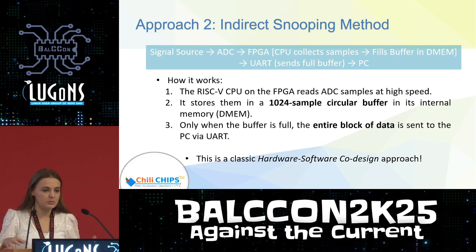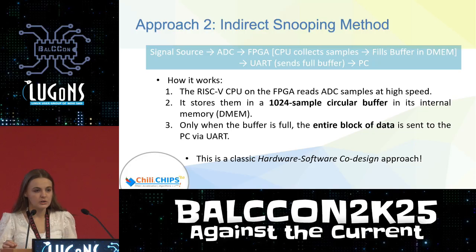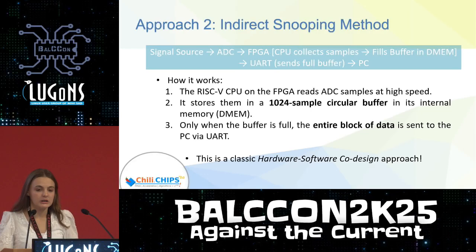So we store the samples in DMEM, so data memory, which is internal to the FPGA. We chose a 1024 sample buffer, which is a circular buffer, so we store it in the internal memory. Then after the buffer fills up to its full size, we send that to the PC in one entire block. So yeah, this is a hardware-software co-design approach.